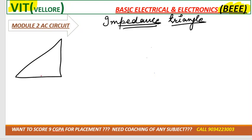In the base we'll always take the resistor resistance R. In the perpendicular we'll always take the inductor resistance XL, or the capacitor resistance XC, and the hypotenuse would be Z, the impedance. The angle between them is always phi. Clear? Now you need to apply the formulas.